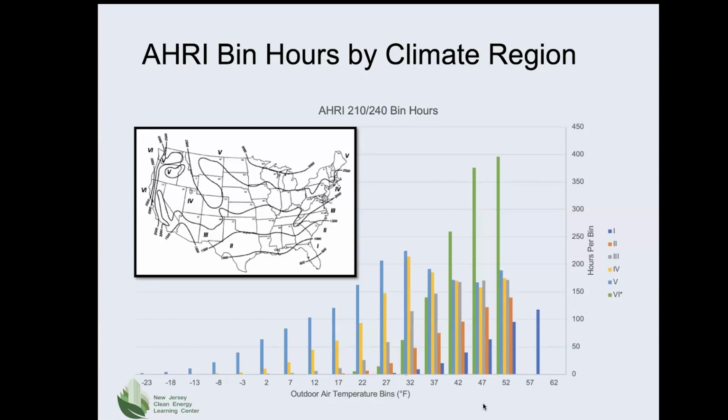And why is that important? Well, it's important because in order to cover this range efficiently the heat pump should be able to modulate its capacity. And the most important part of that range where you are modulating the capacity is between 22 degrees outside air temperature and 52 for the climate zone 4. The other hours that fall outside are very few and far between.